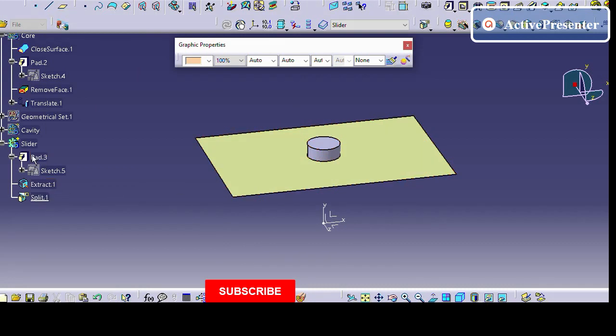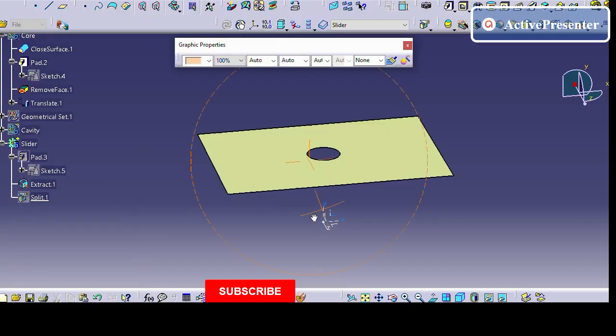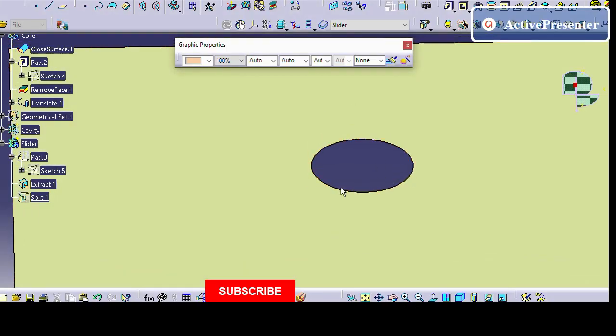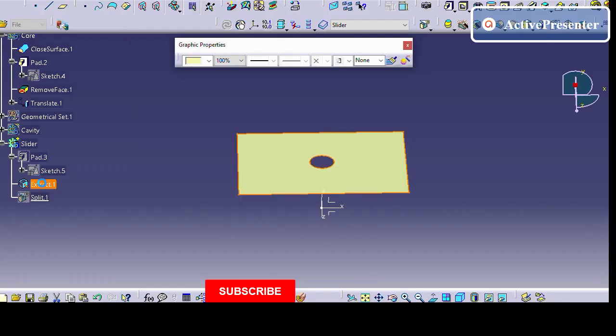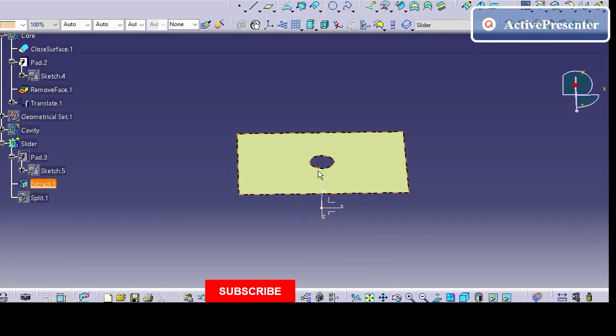Okay, sorry. What is happening here is, see, at the center we have this hole, right? That is why it is not splitting it. So what we have to do is, in the surface, we have another option. Whenever you have, I just want to fill this one, you can do the fill option, otherwise you have another option called untrim.